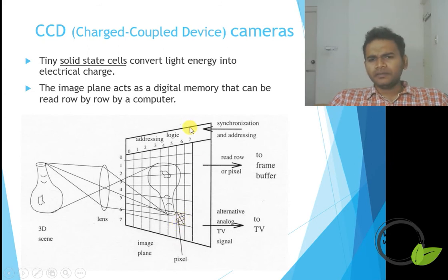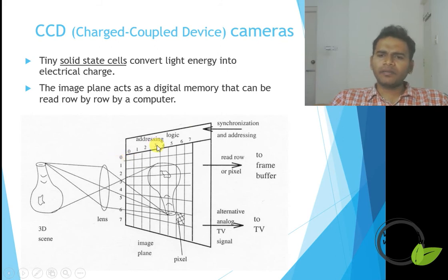Here the primary thing is, how does the scan happen? The scan is a very simultaneous process. It happens in both horizontal and vertical directions in one flash. The minimum time required in the case of charge coupled devices is in terms of nanoseconds to milliseconds. And then how this data is transferred onto your frame grabber, let us talk about this frame buffer or frame grabber in the later part.